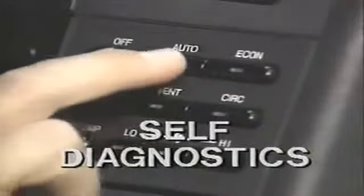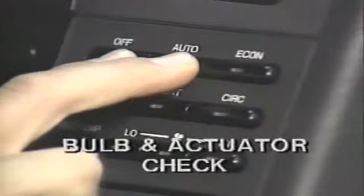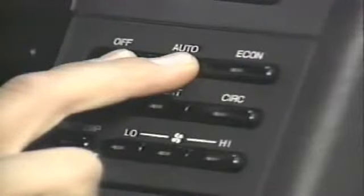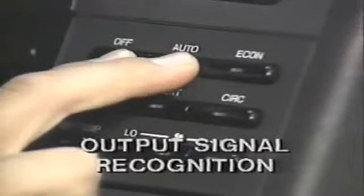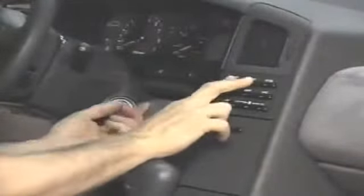There are three modes within the self-diagnostics program: the bulb and actuator check mode, the fault code display mode, and the output signal recognition mode. To start self-diagnostics, the ignition switch should be off. Depress and hold the off and auto switches, then turn the ignition switch to the on position.